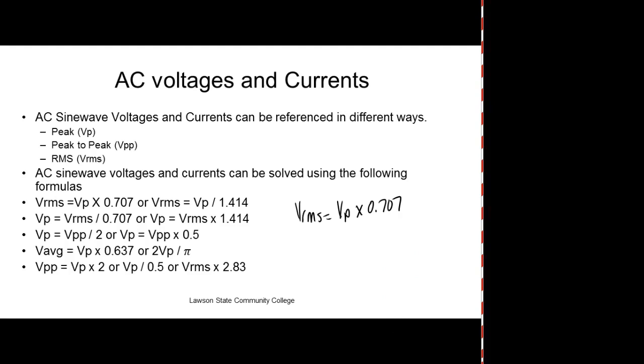And this works great for sine waves. Alabama Power generates sine waves, right? You understand that? So it works great for power. It doesn't work great for AC waveforms that are not sine waves. So if you're in a field that deals with AC waveforms that are not sine waves, what type of meter do you need to buy? This guy right here wouldn't work. It would read something, but it would be inaccurate. This meter right here uses 0.707, which works with sine waves.